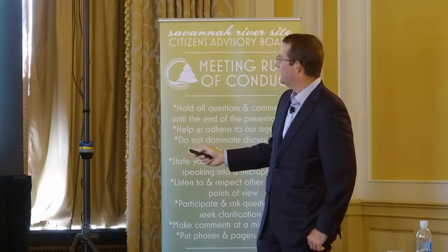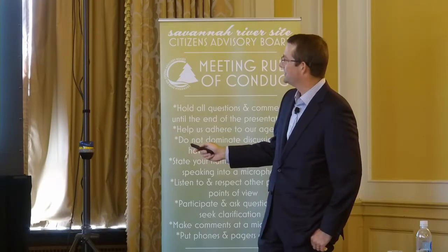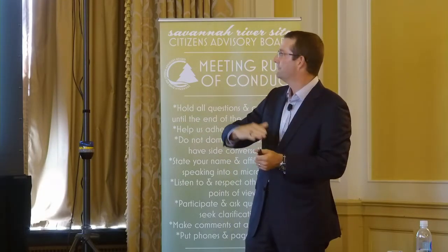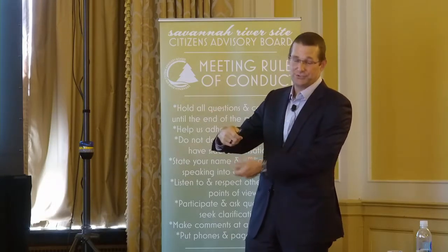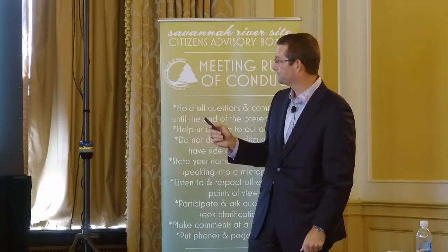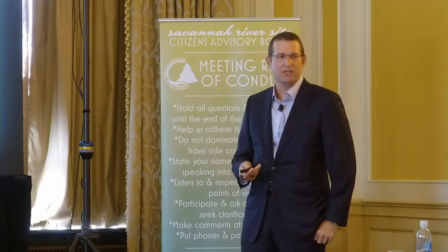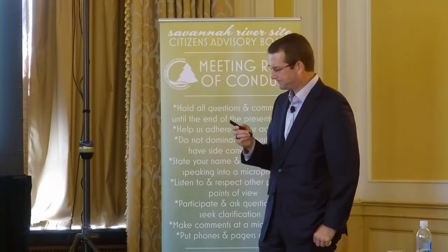And effectively what you have is a rubber hose that comes in the bottom and makes a 180-degree turn to the top, and there is a pressing shoe on the inside that rotates with the motor, and that pressing shoe squeezes that hose like a tube of toothpaste, forcing material down the transfer line with the vacuum behind the pressing shoe pulling in fresh material from the hopper. It has a maximum output of about 180 gallons a minute, and when we are typically operating, we're flowing grout at about 135 to 140 gallons per minute.